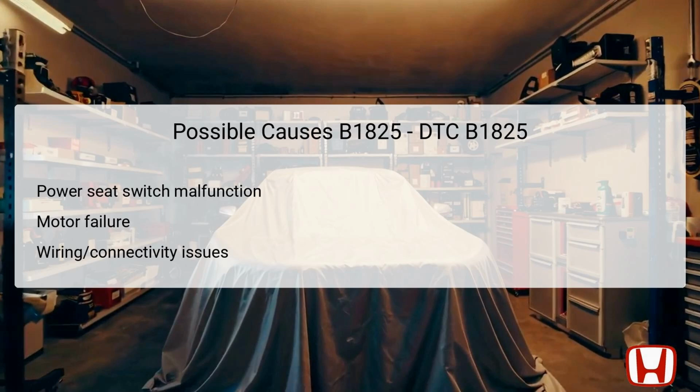Lastly, wiring problems, including broken wires or faulty connectors, could inhibit adequate communication between the control unit and the slide motor. Moreover, thermal stress and wear and tear over time could compromise the included wiring harness. Each of these causes must be investigated thoroughly to ensure all components function correctly.